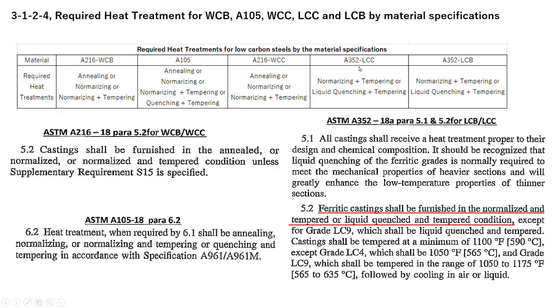So A352 LCB casting and LCC casting are both materials for low temperature service, so the A352 material specification requires the heat treatment of normalizing or liquid quenching.